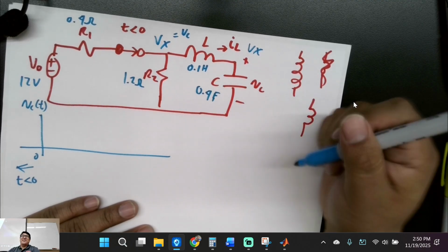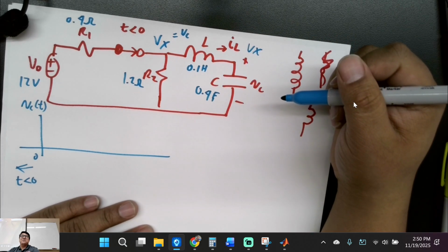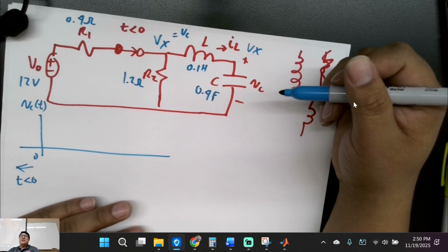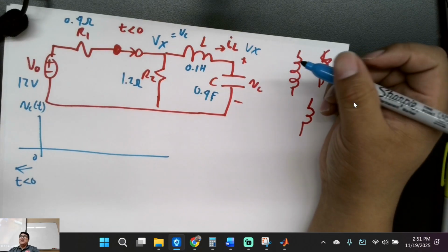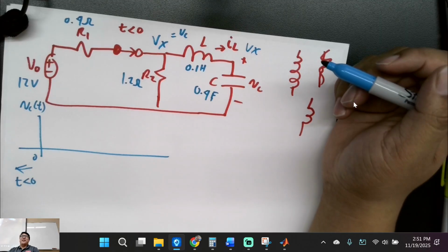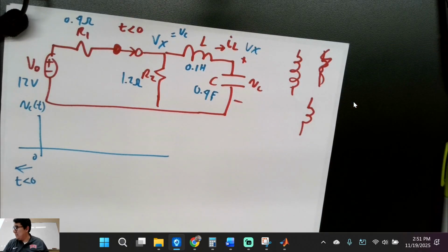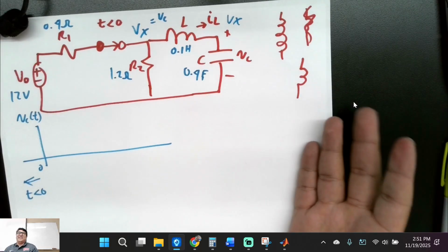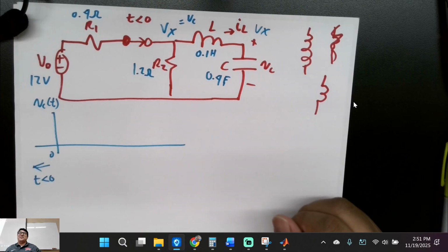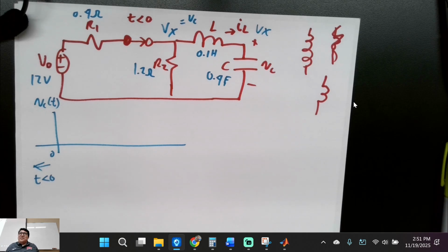What's the current in this circuit then? Actually, what's the current in this capacitor? What does two metal plates in this circuit act like? It's an open. I don't have two plates on me, but think of it like two plates sandwiched like this. There's nothing to connect it. I like using analogies. So no DC current is going to go through that. 0 current.